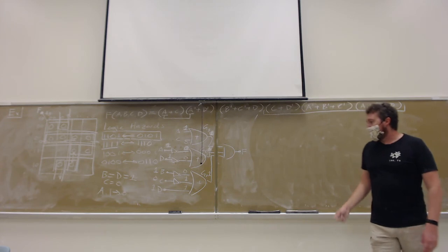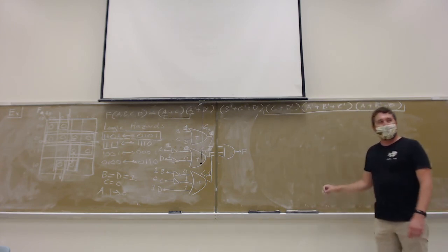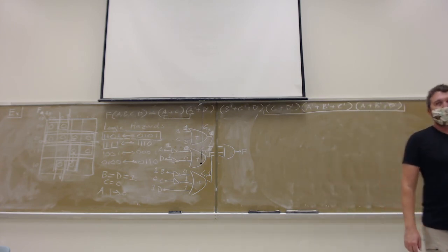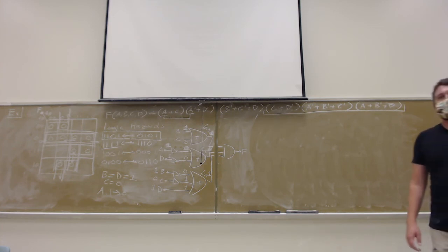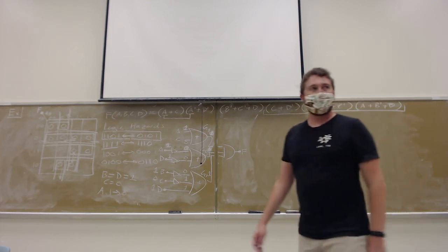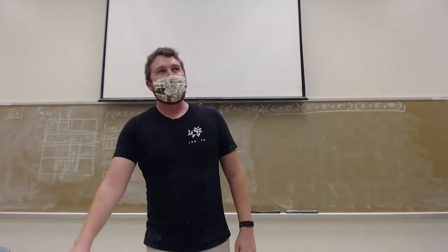If the consequences of the logic hazard are a few rounding errors in a calculator, it's probably better to just go with the more optimized solution, right? But of course, if the logic hazard means the missile explodes in the silo instead of where it's supposed to be, then you probably want to cover up those logic hazards.